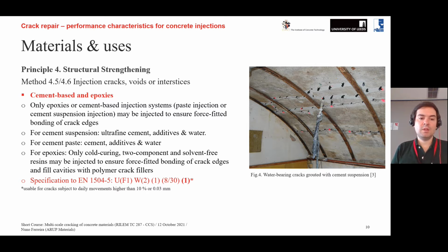And for epoxies, we are talking about cold curing two-component resins that are injected. These are probably the most widely used in the market available today. But bear in mind one thing: you cannot really inject large cavities with epoxies.